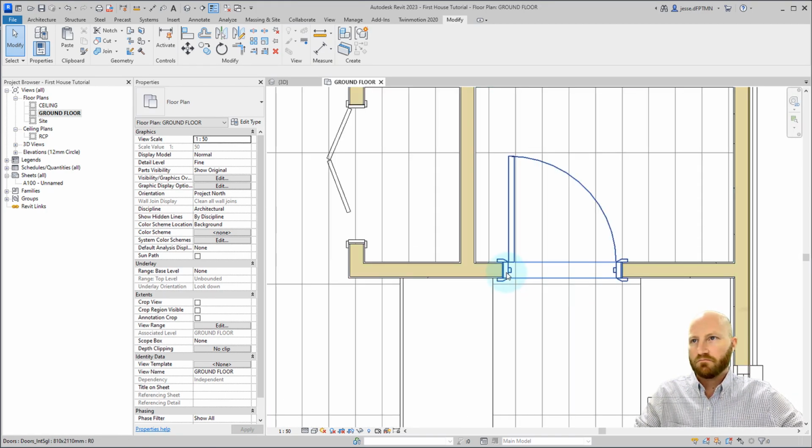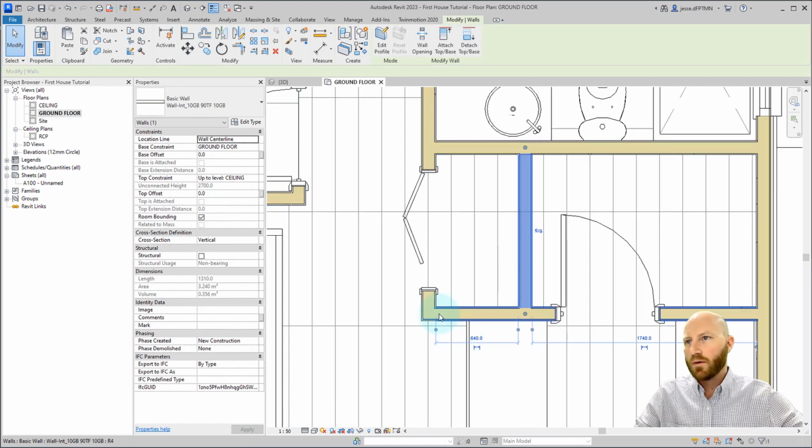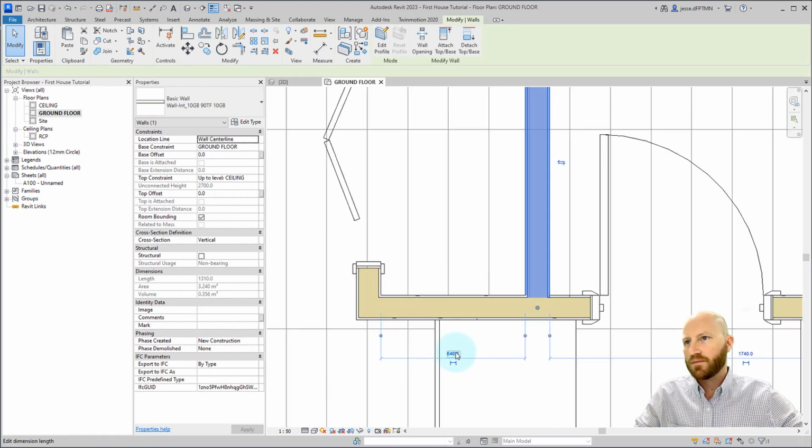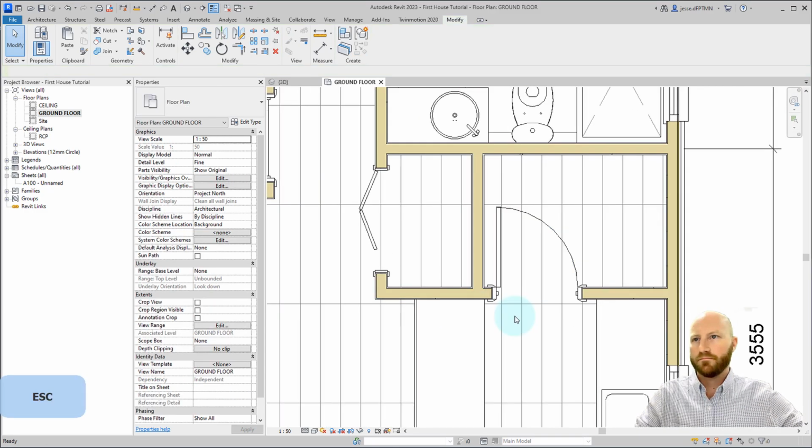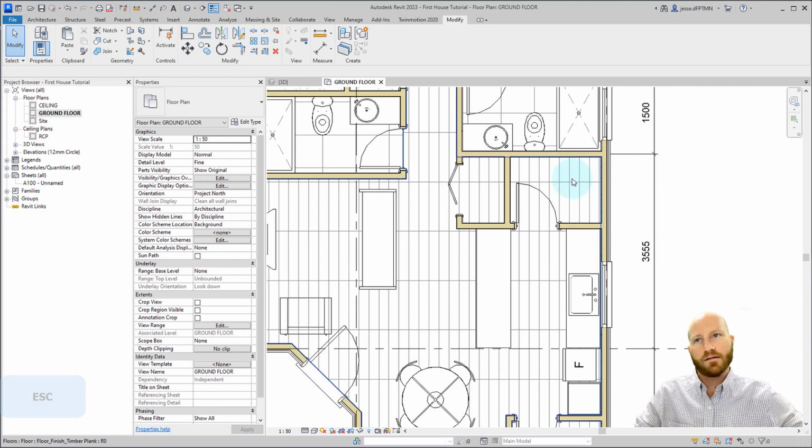This is sitting fairly well inside there, but what we want to make sure is that our interior space here is 750. Perfect. Now we've got a nice little pantry in the back corner. We've got a space for a laundry. That's why we went 750. You could go 800. It's probably a little bit better.